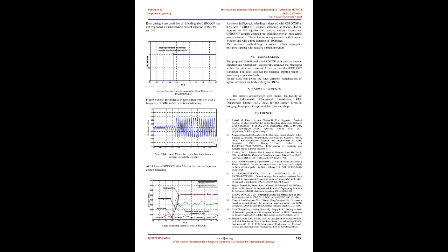But the frequency drift is very small when the active power mismatch is low or 0. So for such small deviations, which are within the zone, microgrid need not be islanded. Hence the real scenario is identified 16,17. For small variation of frequency the RCOF cannot identify the islanding. The disturbances may be due to load switching transients.